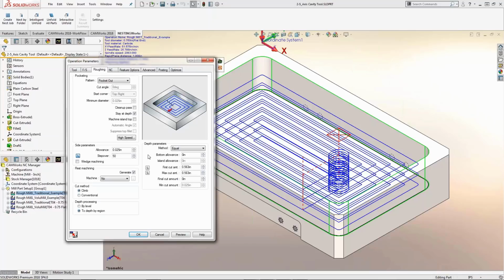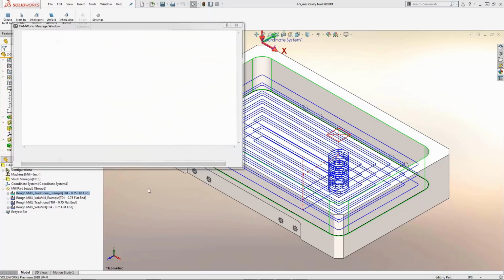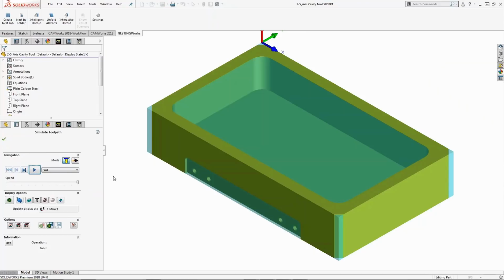To make sure that I compare apples to apples, I utilized another program that's part of the CAMWorks installation. It's called the Milling Advisor, used to maximize the roughing portion of this particular geometry. I specified my depth of cuts and also my step over here, which is rated at 50% of the diameter of the tool. If I toggle it, you can see that it's stepping over 0.375. Now let me hit preview and start stepping through this.